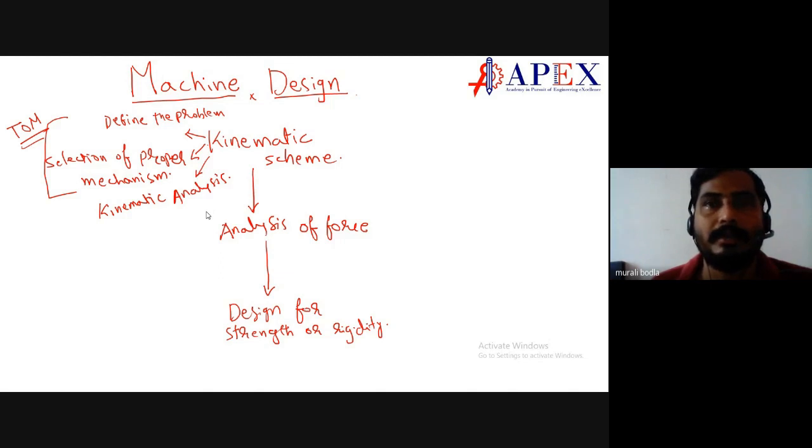That is what is required, because in the theory of machines you might be studying degree of freedom. We will be trying to have a constrained motion. We will have different elements, connecting them, pairing them, but in the end, whether they give a defined motion or not is what is important for us. In all engineering applications, we try to get a degree of freedom of 1, so that you have a defined motion and can work with them. In what direction it is moving, and how we can control it, can all be done. These are all part of your theory of machine study.